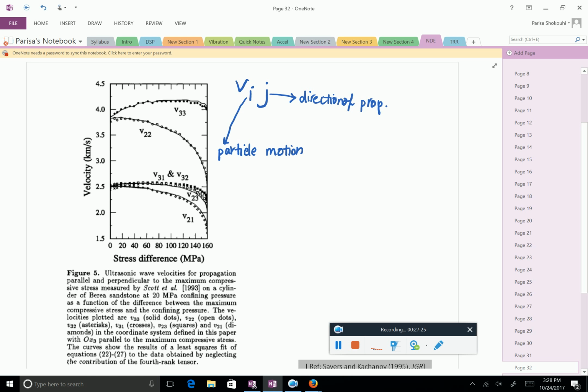What happens when you increase the stress? You go out of the elastic region. So in terms of, for rocks or for concrete, you start to develop macrocracks. And then last time you saw the relationship between velocity and macrocracks. So as you get more macrocracks, then the velocity is decreasing. And then this is what you are going to see. So there is kind of two mechanisms which are competing. One is here acoustoelasticity, crack closure macroscopically, and then they're competing, and then macrocracking takes over.